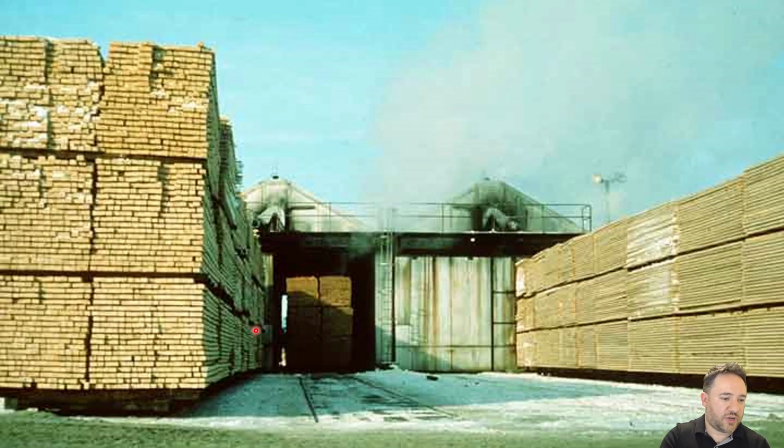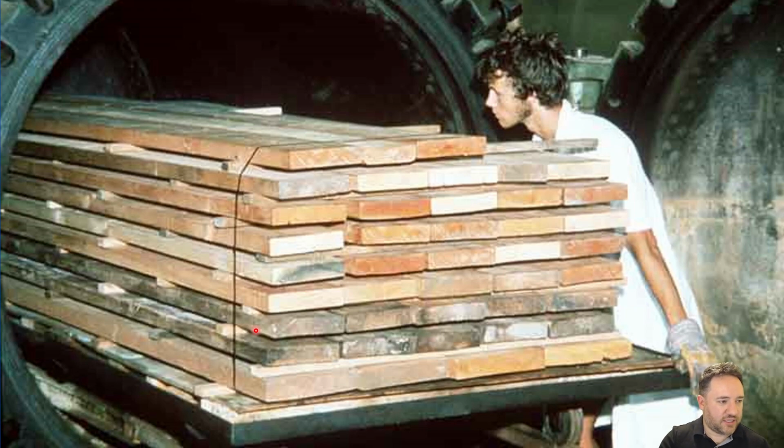So here's some kiln drying so that we can deliver the wood to site at an appropriate moisture content. We don't want to distribute green wood. Here's the kiln. I think this is a pressure treating oven, actually. So one of the things that we can do instead of going after the air or the moisture is that we can actually poison the food. That's the process of pressure treatment, basically putting a chemical into the wood and impregnating it using a pressure vessel in order to make the wood unpalatable to the fungus.